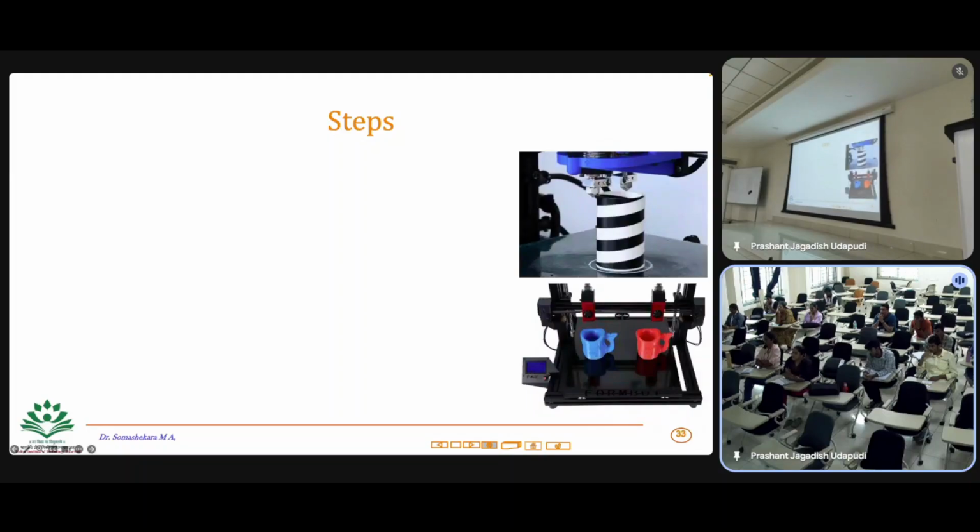For example, sometimes you may have differences in terms of the materials. So you can also use different nozzles for making different material depositions. For example, you can print two color materials within the same nozzle, but then you need to change the input material. Instead of changing the input material, why don't you have two separate nozzles with two different colors, so that it is easy. At some time you can use a different color nozzle, and then you can have separate color components.